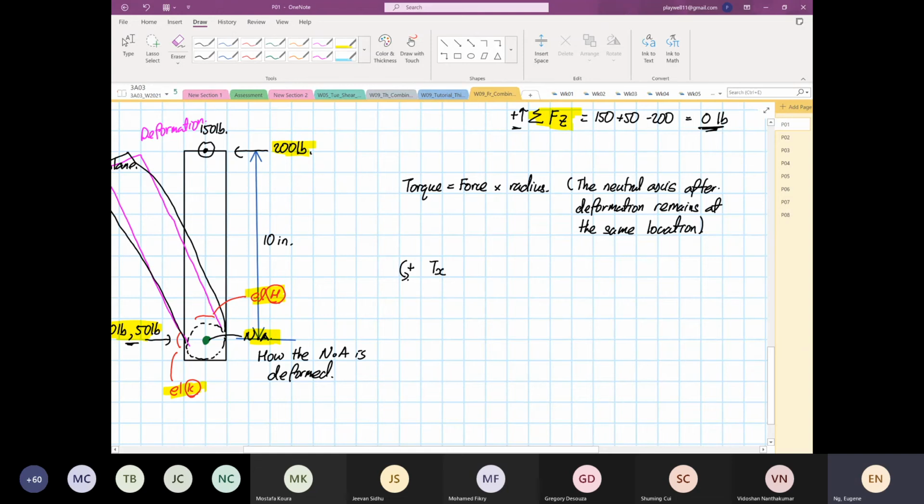Anyway, so now torque is in the x-axis. So we have FOS, factor of safety. If you know what you're doing, the factor of safety, depending on the application, can be 1.3 to 1.5. If it is dynamic loading, you usually put a bit more.